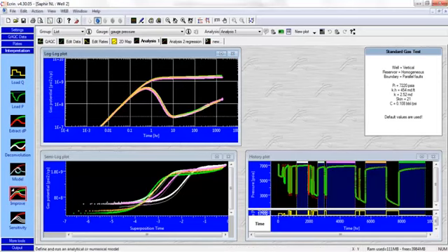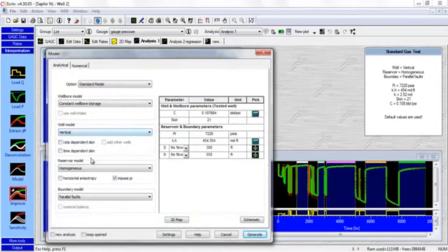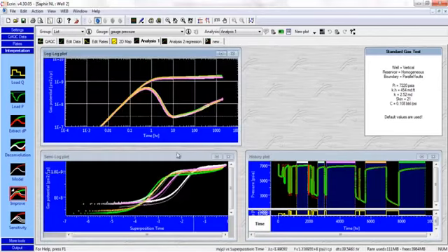We matched our data with an interpretation model using a vertical well in a homogeneous reservoir, with the presence of parallel faults. Homogeneous means a single layer with uniform properties throughout, and parallel faults at 300 and 550 feet from the well. Small permeability, 2.5 millidarcy, and a high skin, which might imply some limited perforation. You can see this large skin with this large hump here.